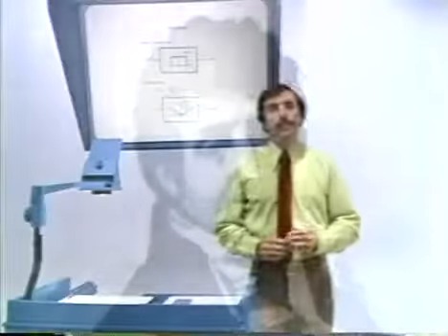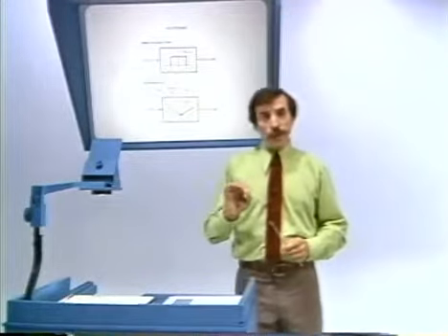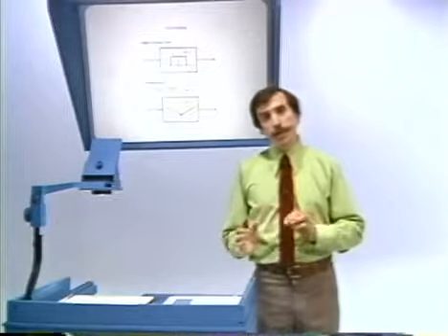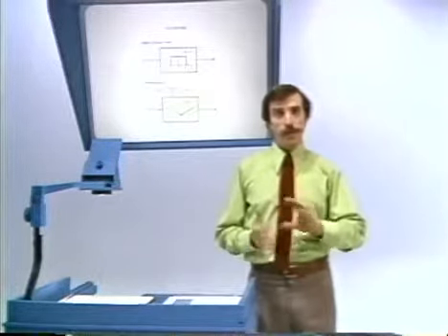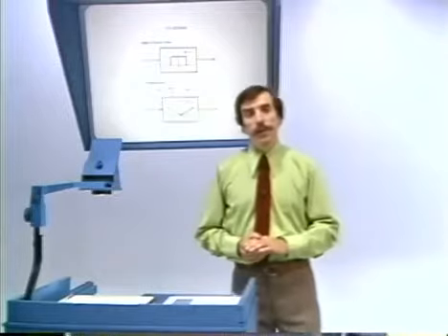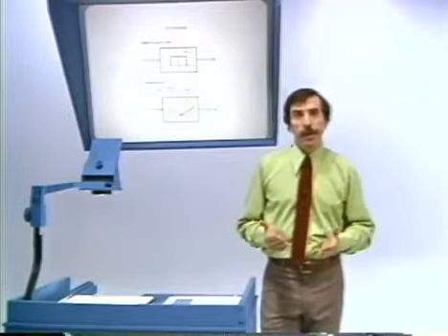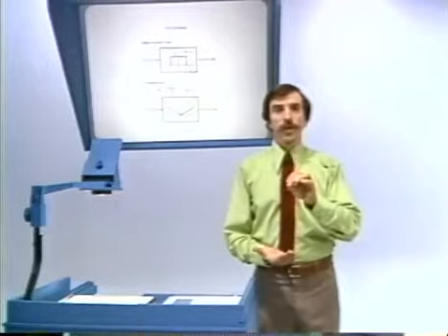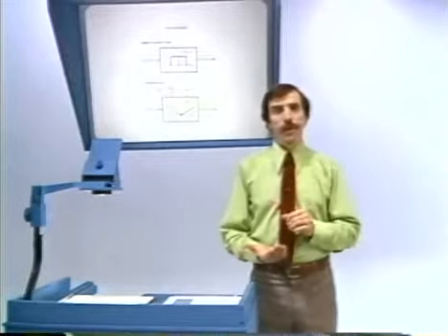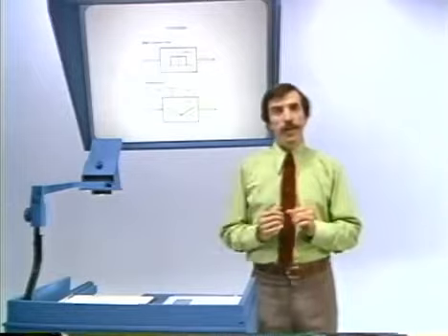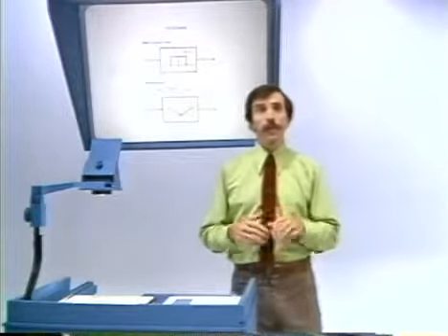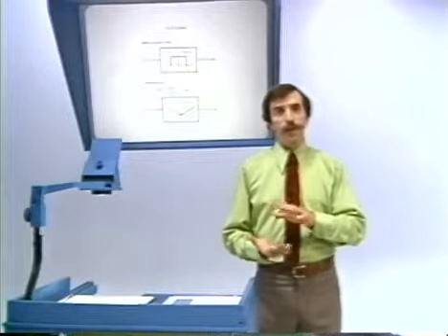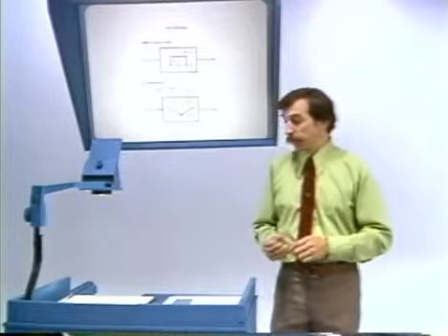Okay, now what we can also consider is what would happen if we looked at the differentiated image, and there are several ways that we can think about this. One is that the output of a differentiator, of course, is larger where the discontinuity or where the variation is faster. And so we would expect the edges to be enhanced if, in fact, we differentiated the image.